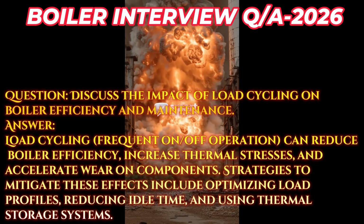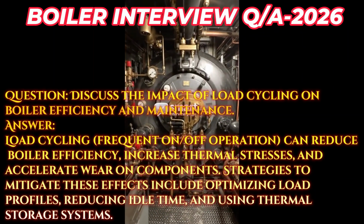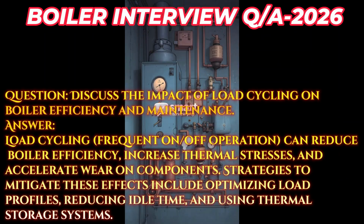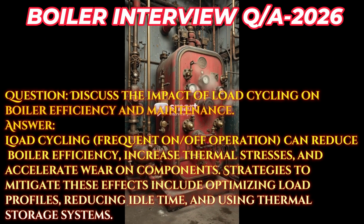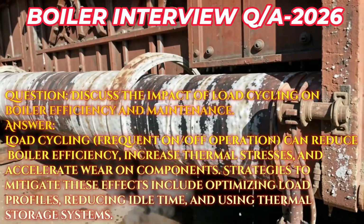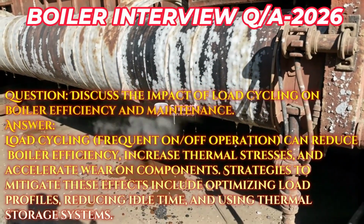Question: discuss the impact of load cycling on boiler efficiency and maintenance. Answer: load cycling, frequent on-off operation, can reduce boiler efficiency, increase thermal stresses, and accelerate wear on components. Strategies to mitigate these effects include optimizing load profiles, reducing idle time, and using thermal storage systems.